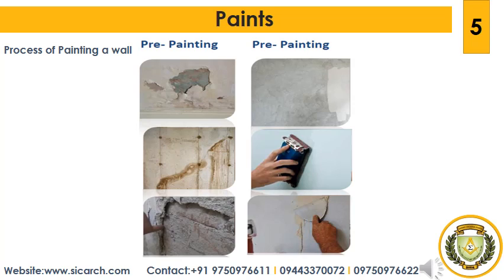The ready-mix paints are normally expensive and they are to be used soon after opening the sealed container, because the volatilization of the vehicle and solvent will start taking place when it is exposed to atmospheric oxygen. If the ready-mix paint is kept exposed to air for a very long duration, the solidification of the base